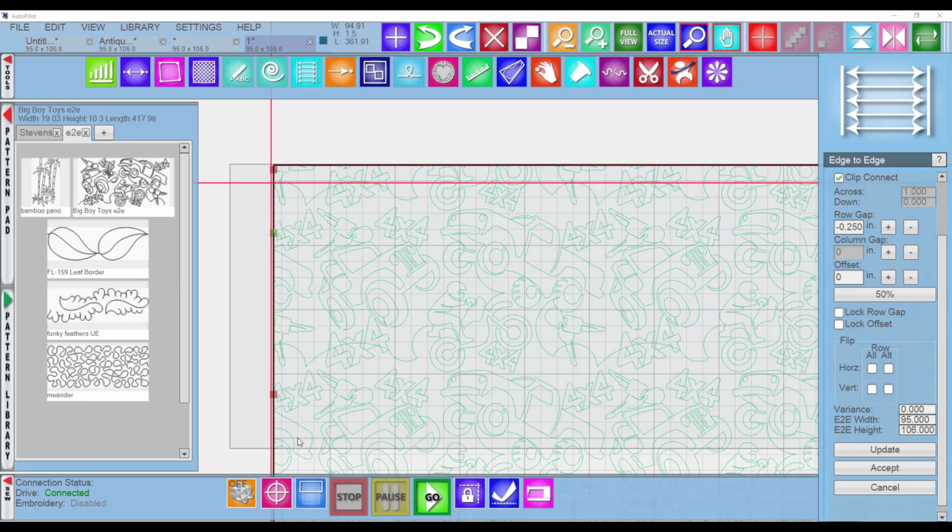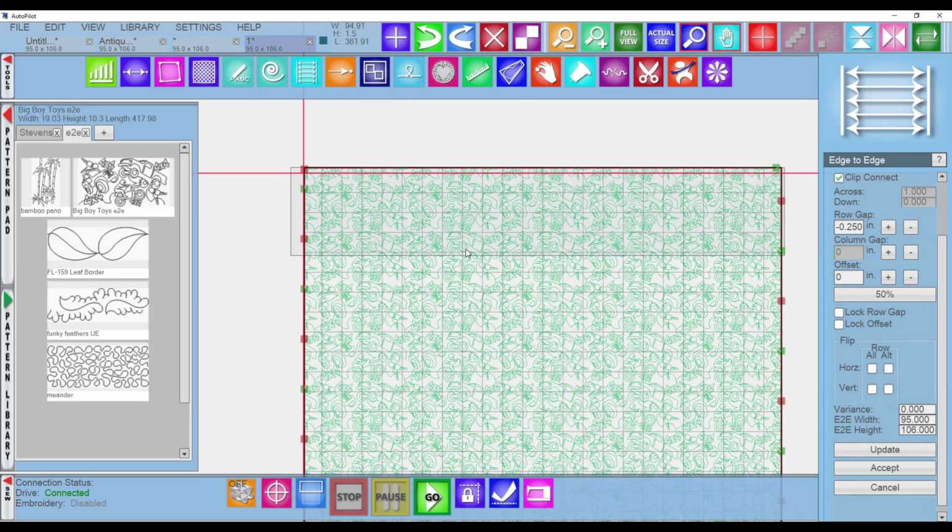These next two icons are a little confusing to people, especially who are new to the machines. So let's start with the sew zone, the blue icon. When you load your backing and start maybe basting on your quilt top, if that's how you do it, you'll want to set up your sew zone. So at the beginning of every quilt, you will set this up. And it's basically the safety zone where your head knows it's not safe to go off the edge of that, because if it came back on, you could certainly tear a quilt, which would be a bad thing.